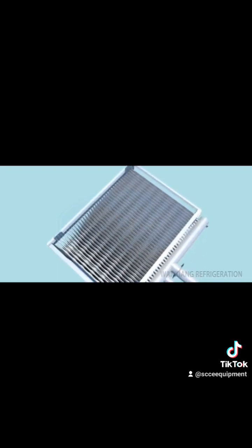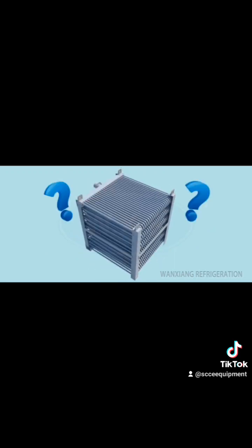Advantage 2. Simple maintenance. All plates are installed vertically and equally spaced. In case of a leak, the spotting of the leak location is simple. The bad plate can be cut out and replaced with a new one in the shortest possible downtime. This is not true with a tubular coil type condenser. It is an extremely difficult task to locate a leak in a tubular coil, especially if the leaking tube is located in the inner rows. Once the tube is located, all we can do is plug it, which means a drop in capacity.